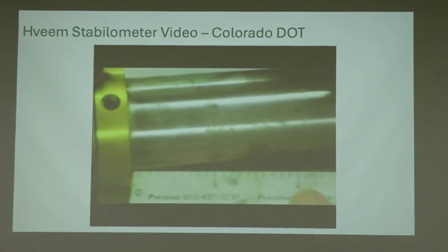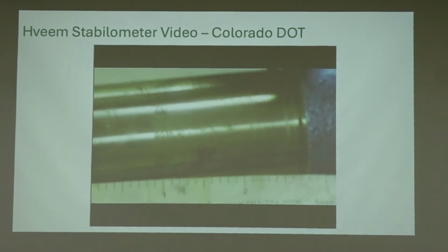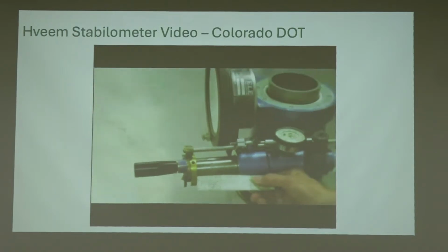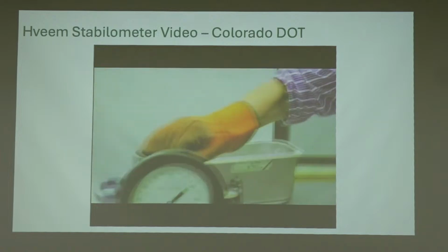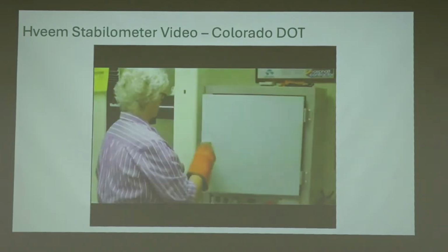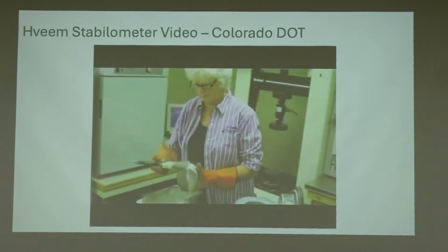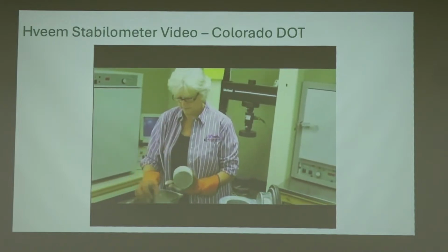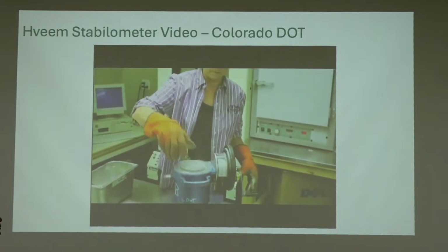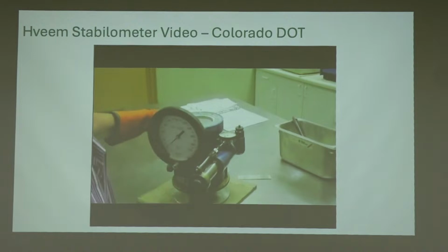So with the calibration cylinder still in place, with it set at 5 psi, you'll measure the exposed piston length, which needs to be 2.8 plus or minus 0.2, which tells you if there's enough oil in the bladder. So you'll be taking the calibration cylinder out then, and you'll be removing a specimen from the 140 oven, placing powder around the outside of your specimen, or you can actually put powder on the inside of the stabilizer bladder. Allow it to slide down into the stabilizer. If it doesn't slide down, turn the handle out till it easily slides down.